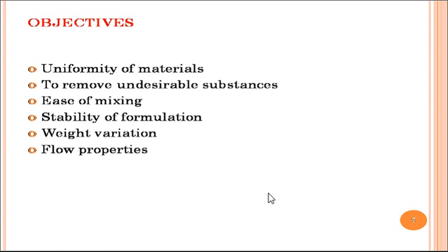Say, for example, in case of tablet manufacturing, granules are required to be size separated by passing through the appropriate sieve number to maintain a unique flow property, and that is required to maintain a unique volume to be filled in each die, and that's why we are getting tablets of unique size. That is the main reason why we are using